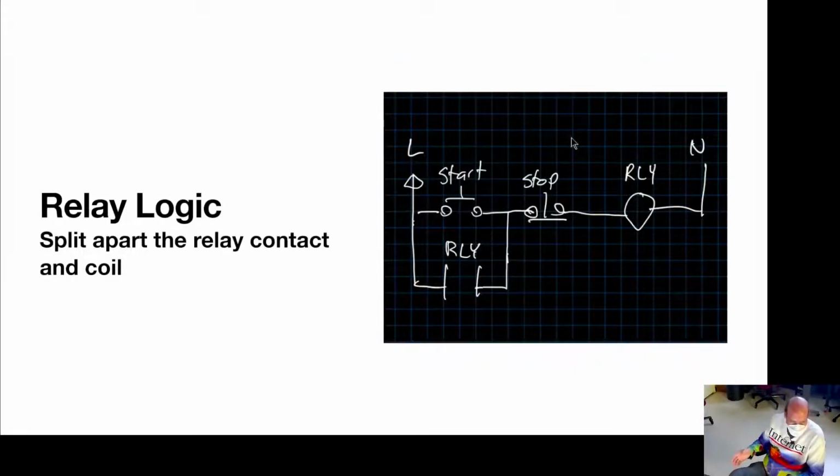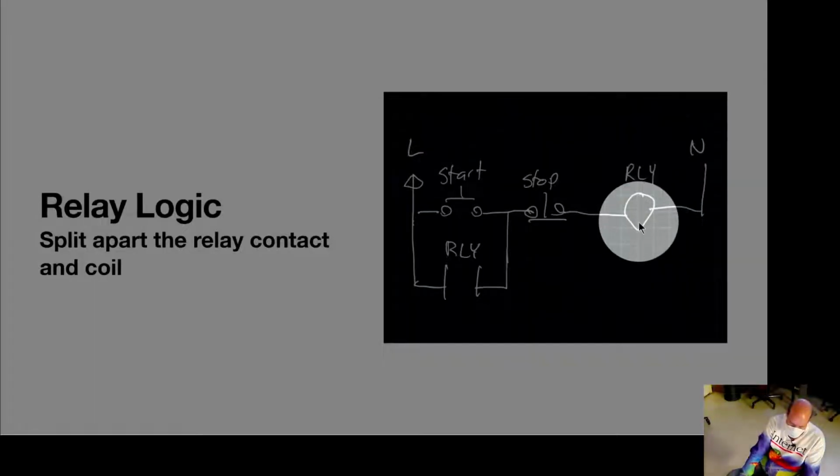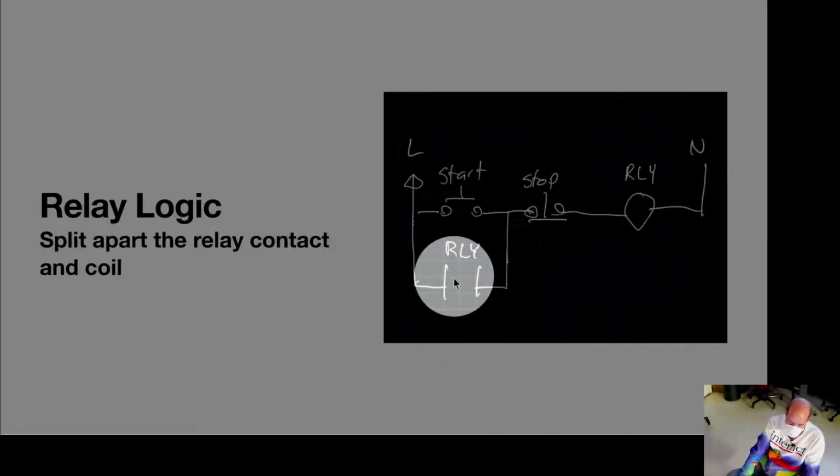If we are drawing a lot of these, it makes sense to move the display of the relay coil and the contacts somewhere else in the schematic, because even for the previous example, you're going to have contacts for this, which powers my motor, and then this is my contact for latching the on, off, start, stop button relay on. So the relay coil, in this case, is just drawn as a circle, and the relay normally open contact is drawn as these two bars.